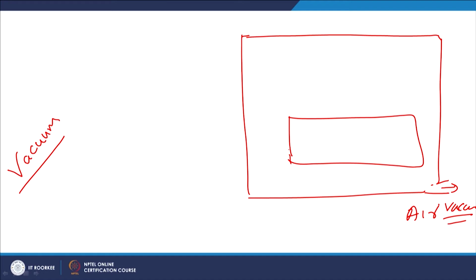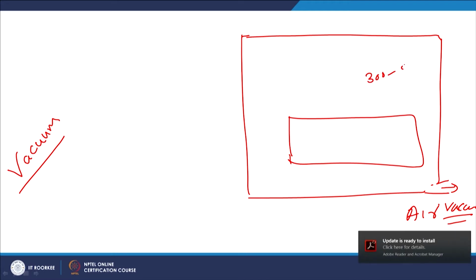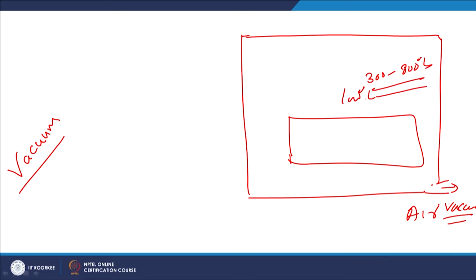Now the temperature is increased reasonably, maybe like 300 to 800 degrees centigrade, or even lower, like 100 degrees centigrade. Such lower temperatures will be assisting the chemical composition modification of the surfaces with the help of the gaseous mixture which is being fed.